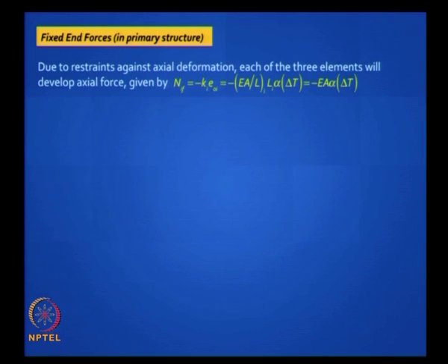We put a minus sign in general because normally you have a rise in temperature and e naught is an extension, right? But in this case e naught will turn negative, so when you substitute the results you should get a tension, right?